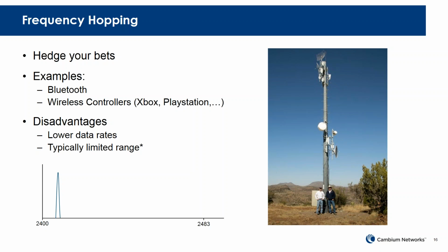They shouldn't, except that solar panels tend to be very flat. So if you're shooting past the solar panels, it's possible that you can get reflection and multipath. But as far as any kind of interference from a radio perspective, you really shouldn't, as far as I know, get any kind of interference there. That's a good question. You want to avoid mounting it in front of the radios, but you'll probably be okay. I've at least not heard of anyone having problems with solar panels.